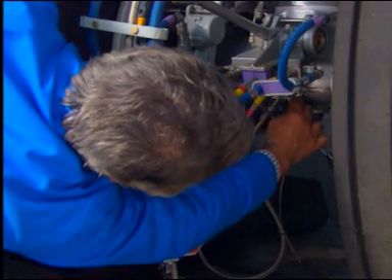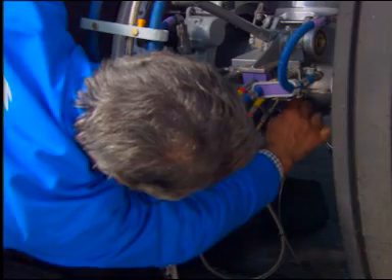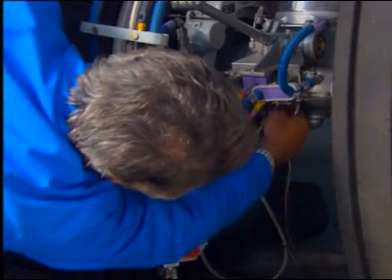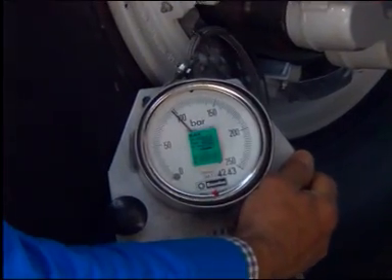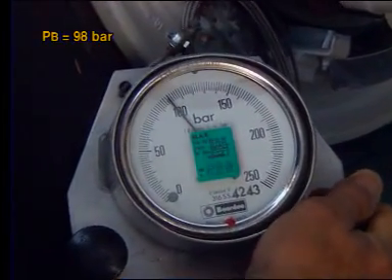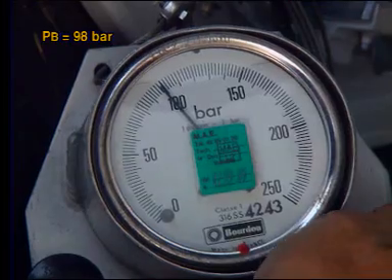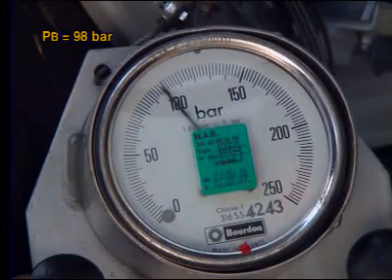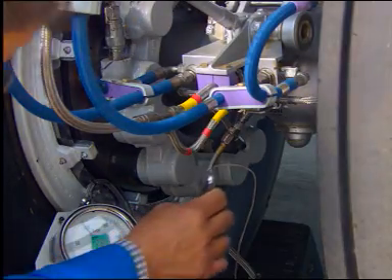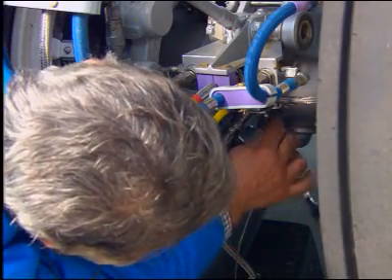On the bottom charging valve, the nitrogen supply being open, open the bottom charging valve. Open the control supply valve slowly to add nitrogen to the bottom chamber. Close the bottom charging valve.